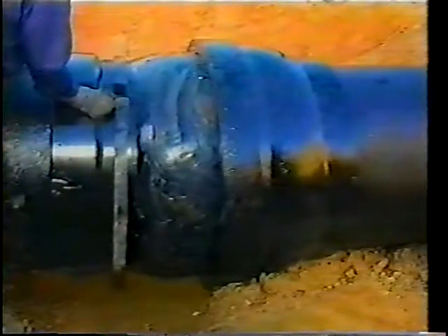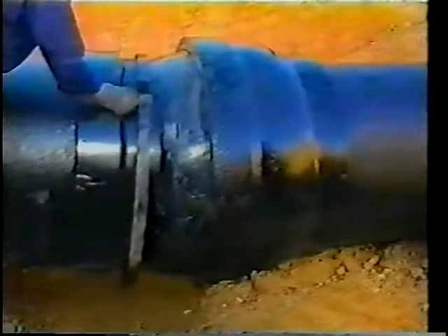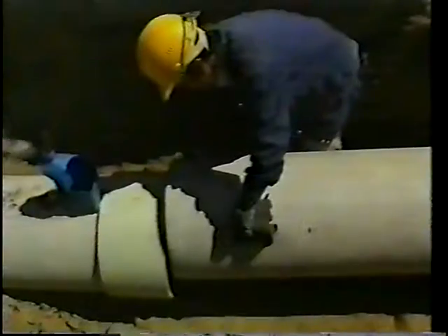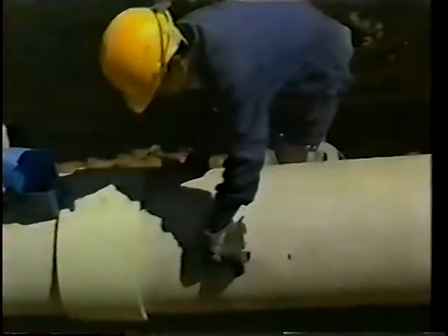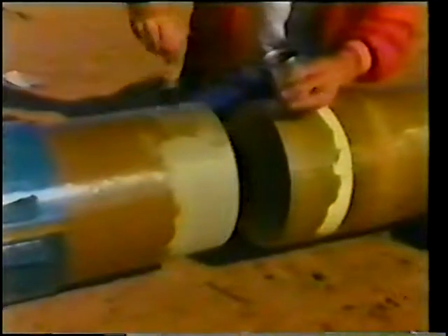Ball and socket joints can provide a flexibility up to 15 degrees per joint. These can be useful for locations with changes of grade or alignment, subaqueous crossings, and in seismic areas. Some fiberglass pipes have push-on joints, and some have mechanical locks, which require only a lubricant in the field. For others, adhesive is applied to both ends, which bond together.